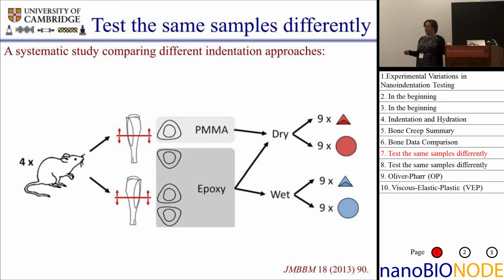And I'll note, because George did comment on this, we use relatively large spherical indenters to keep the strain small to make sure that we have no plastic deformation, whatever that means in bone, and I'll come back to that. So we're using relatively large sapphire probes, so they're much better in terms of roundness than what people get when they try to have diamonds that are relatively small.